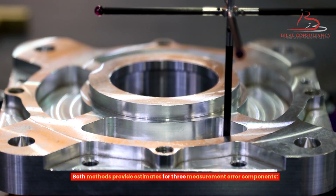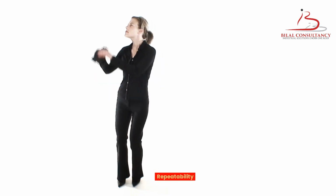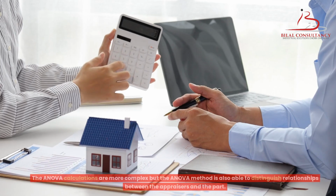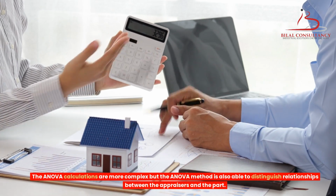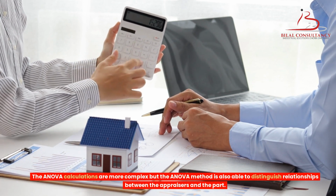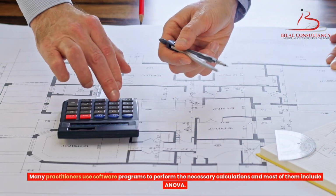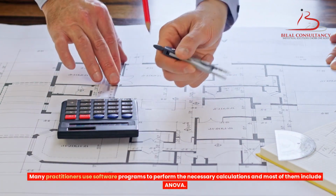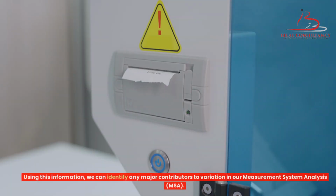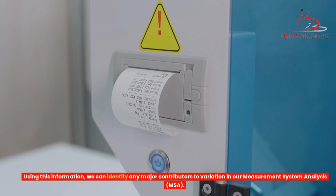Both methods provide estimates for three measurement error components: repeatability, reproducibility, part-to-part variation. The ANOVA calculations are more complex, but the ANOVA method is also able to distinguish relationships between the appraisers and the part. Many practitioners use software programs to perform the necessary calculations, and most of them include ANOVA. Using this information, we can identify any major contributors to variation in our measurement system analysis, MSA.